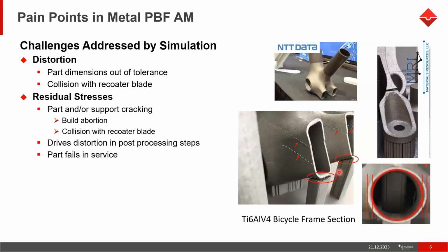And sometimes when you build these parts, we take the help of these supporting structures. These support structures hold the part during the manufacture, because we have to manufacture these parts in the machine. In the machine, there will be a base plate on which this part will be manufactured layer by layer. So we have to keep this part in different orientations, different angles to manufacture actually. We can't place the part simply like this as it manufactures. We have to take help of these things called support structures, which will be attached to the base plate along with the part actually.